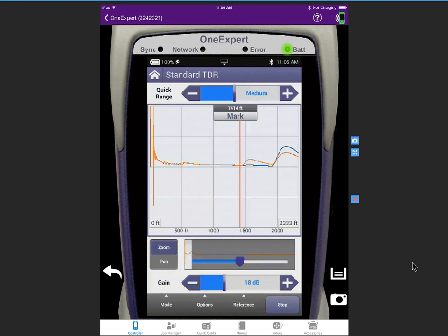Technicians think that TDRs run in a continuous fashion. Well, actually, they run in a pulsing fashion. When the TDR is first turned on, the sequence of events goes send the pulse, receive the reflection, and draw the picture. Well, every subsequent pulse after that, the sequence is a little bit different in that it's send the pulse, receive the reflection, erase the previous picture, and draw a new one. Well, what peak does is never erase. So its sequence is send, receive, draw,